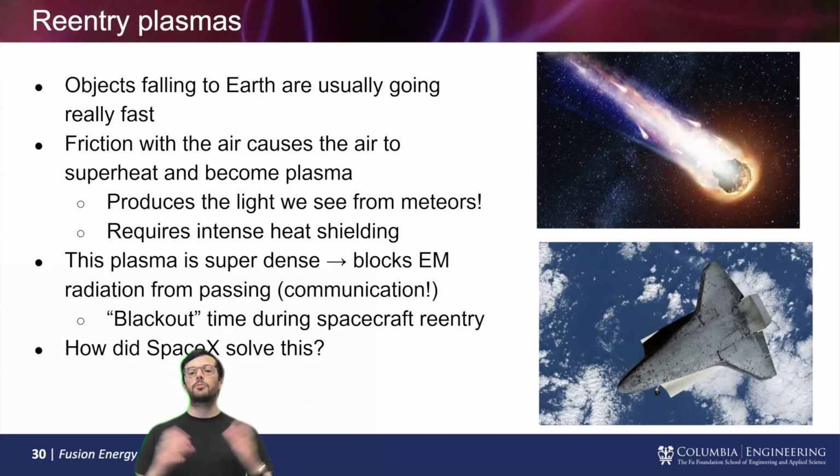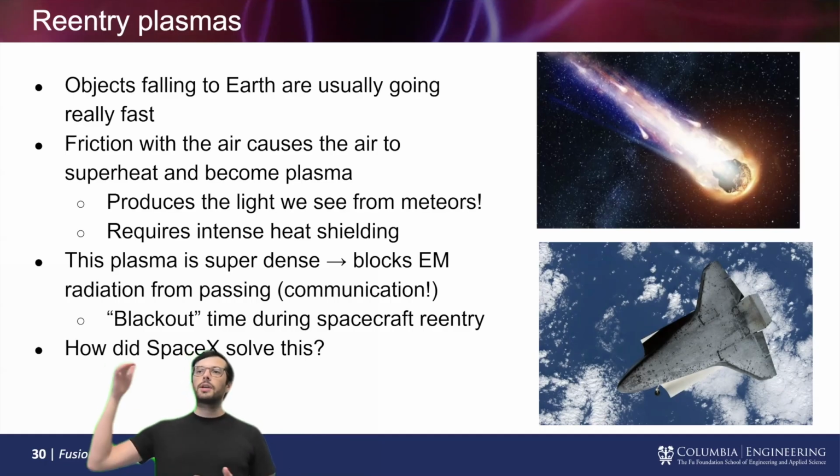But the other thing it does is, now that you have plasma, it actually blocks light. And light is also radio waves and any kind of communication that we might use. It blocks those because they can't go through plasma of a certain density. We will talk about that phenomenon later. But in the case of basically every re-entry vehicle that humans have ever ridden, there's this blackout period. You might have seen it in movies like Apollo 13 or kind of any space movie where they're coming in and there's this period of a few minutes where there's no communication between the ground and the spacecraft. And that's really scary for spacecraft operators because it's also the most dangerous part of space travel.